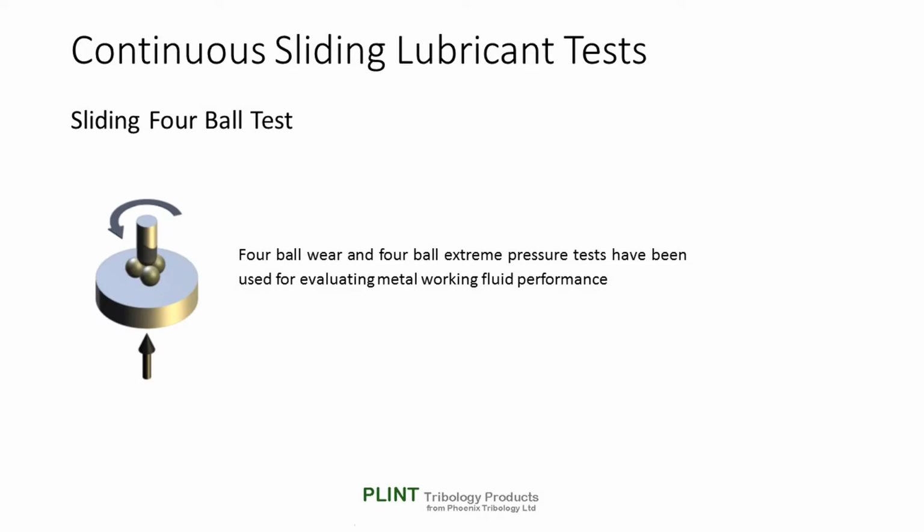Both 4-ball wear and 4-ball extreme pressure tests have been used for evaluating metalworking fluid performance, but it's hard to see how a sliding contact between bearing steel balls models anything much to do with machining, forming or forging.